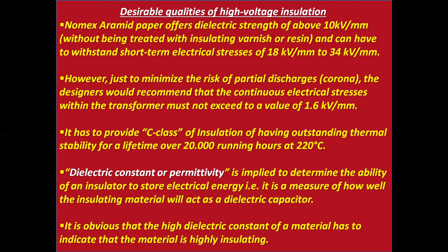However, to minimize the risk of partial discharges, that is corona, designers recommend that the continuous electrical stresses within the transformer must not exceed a value of 1.6 kV per millimeter. It provides C class of insulation, having outstanding thermal stability with a lifetime of over 20,000 running hours at 220 degrees centigrade.